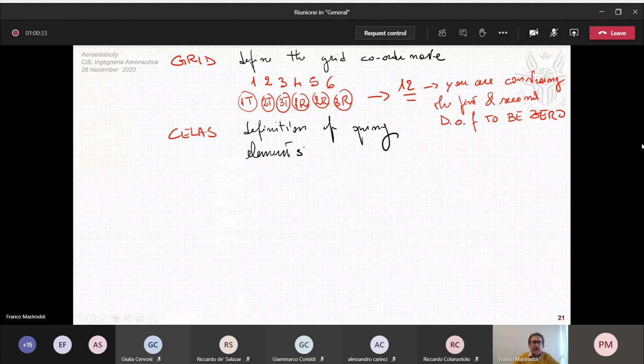So the message is that with the finite element code, you can define finite elements as part of a material, part of a structure, but you also may define concentrated elements, because you know very well that the final mathematical model for a discretized structure or for a naturally discretized structure is quite the same. You always will reach a mathematical model composed by the mass matrix, the stiffness matrix, and so on. So you can also use Nastran for a concentrated parameter model, as we have just now here.